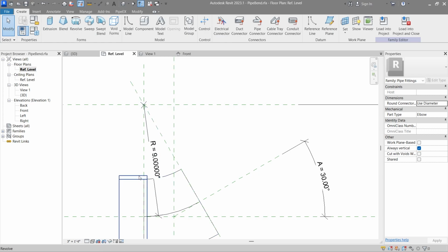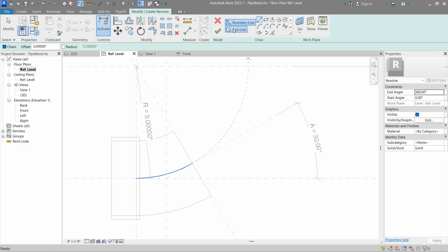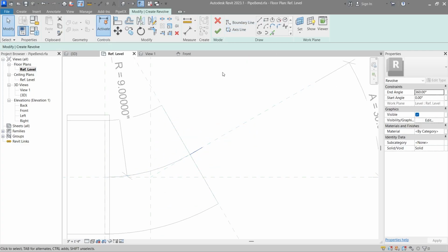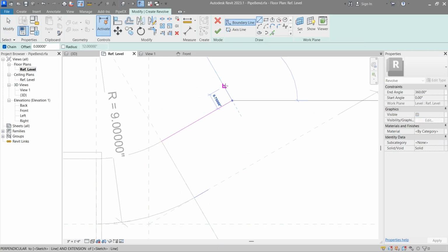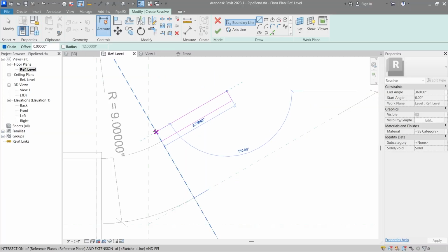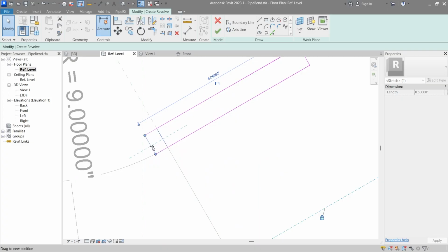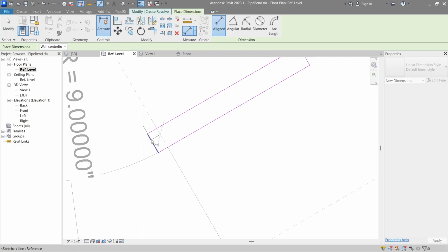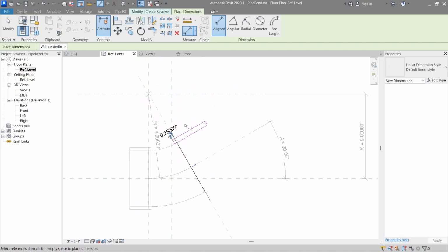And then the next connection also will be done via the revolve tool. First I will start from the axis. And then I'm going to draft the shape of our component. So as it was before, here it also will be equal to 0.25 inch.